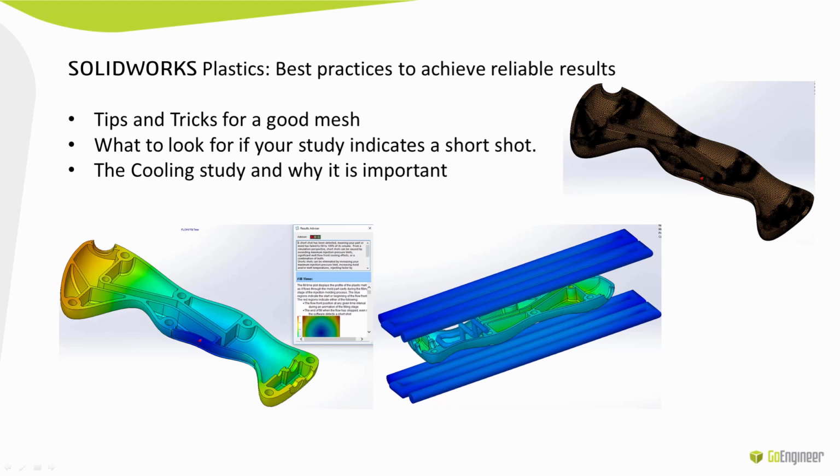Typically, you may get a short shot, your part will not fill. Sometimes there are settings within the system that will throw a short shot and your part's not really going to be a short shot. So I'll go over those situations and what may cause that as well. And then the last is going over the cooling study and why it's important.